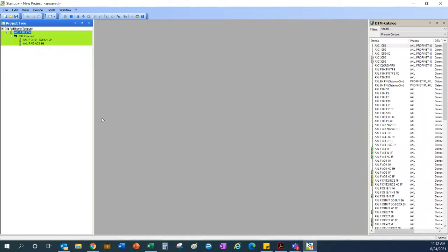If I take this module off and go put it into a different IO station somewhere else on the plant, let's say I'm here working at my desk, I set up the IO station, I pull the IO station, I put it in a box, I ship it to my customer. They can install it knowing that it is ready to go, pre-configured out of the box with no additional changes that have to be made.